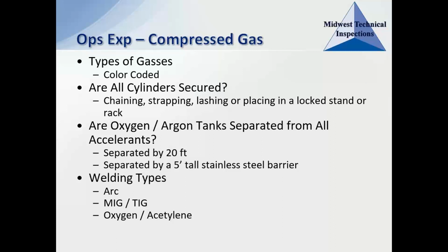But then you can get a little bit more advanced to the MIG or the TIG welding, where now you're using an inert gas to provide kind of like a bubble around the weld. So it's still using electrical arc to vaporize the metals, but now you're putting a non-flammable gas bubble around that weld so that it protects it and keeps dirt and debris from entering into that weld. So now when your metals vaporize, it's just the metal particles that are mixing together and resolidifying. You don't have extra debris in there. So it's a cleaner, stronger weld when you have the inert gas welds.